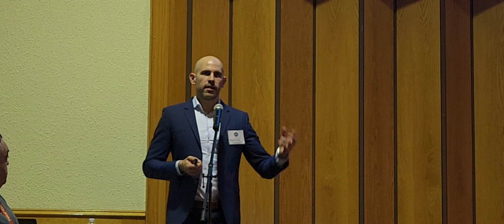Thank you. And I think this grouting is watertight, right? Waterproof, yeah. Let's say if we have a very coarse sand and very high water level, and we want to excavate inside of it, can we use this material to avoid dewatering? That is actually what, for example, in Kitchener earth boring did. They wanted to avoid dewatering, and therefore they injected sealing blocks where they wanted to excavate, where they wanted to open the shafts, for example.